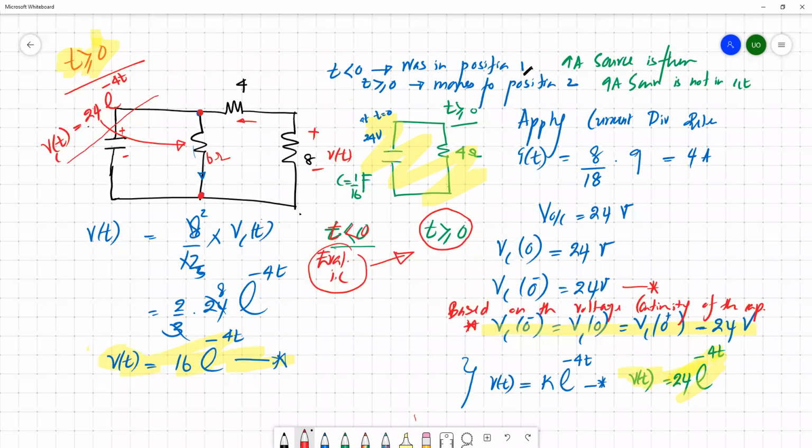So if it is less than 0, it basically explains whether the circuit is in DC steady state or not. If it is not, you can apply the same scenario, but you can't replace the capacitors and inductors with open circuit or short circuit elements. You can keep the capacitors and inductors as they are and find the response. Then, if you want to evaluate the values, you just plug in t equals 0 to get the exact value of the capacitor.